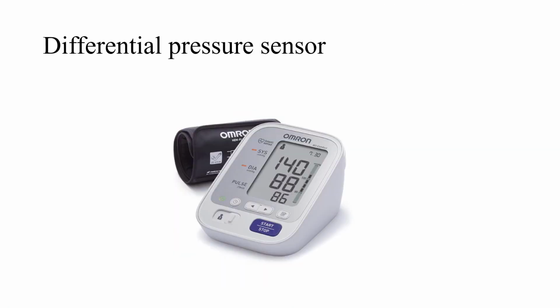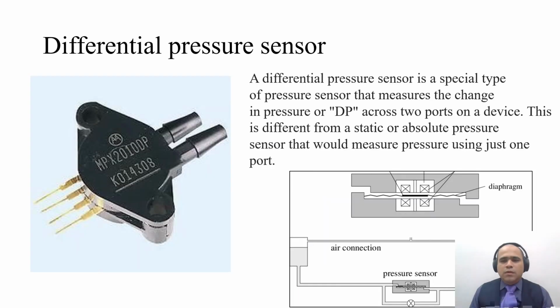Sir, I had a doubt. Which sensor is used in a blood pressure monitoring device? A differential pressure sensor is used in the BP measuring unit to measure how much to inflate the balloon. Otherwise, if you inflate it too much, it will be very tight for that person and could be disastrous. The actual readings are then measured like the pulses that a doctor measures with their stethoscope.